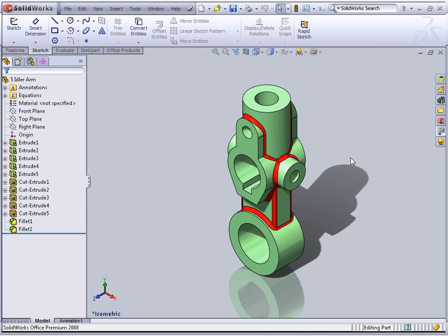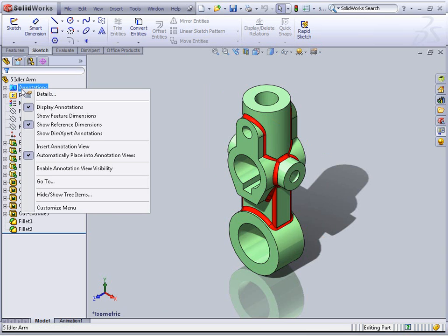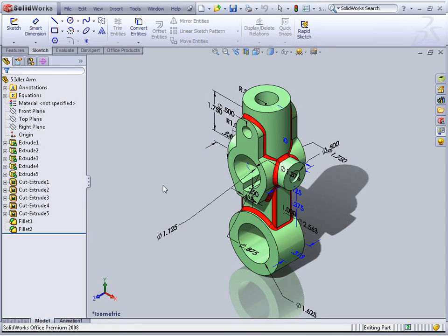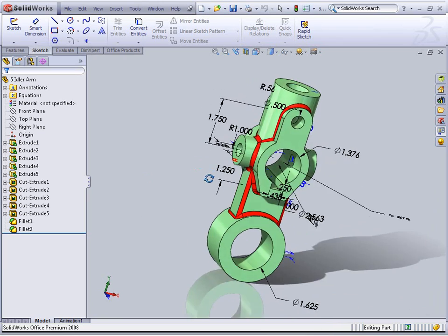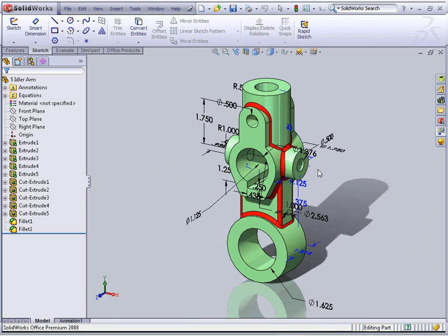So when we showed up and gave you this demonstration of SOLIDWORKS for the first time, we said drawing creation is automatic. Well, we weren't trying to fool you. It's just that we knew how to set the models up, how to plan out our datum structure, and how to bring those dimensions into the drawing. So not all the models will have the proper datum scheme. If I take a look here, the annotations on this part, some are valid, some are not. Okay, but basically all these dimensions can be brought into my drawing.